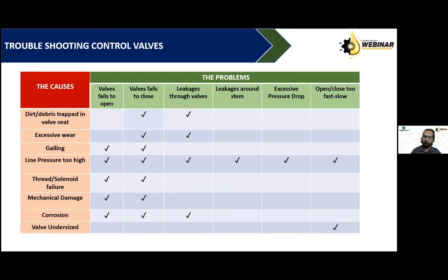Excessive wear will be caused by both solid contamination as well as water contamination. Galling is nothing but damage of component, or sometimes it is peeling off the top surface. This may sometimes be due to subsurface cracks, but when moisture content oil enters in those areas and during high pressure, they burst and they chip out the top layer.